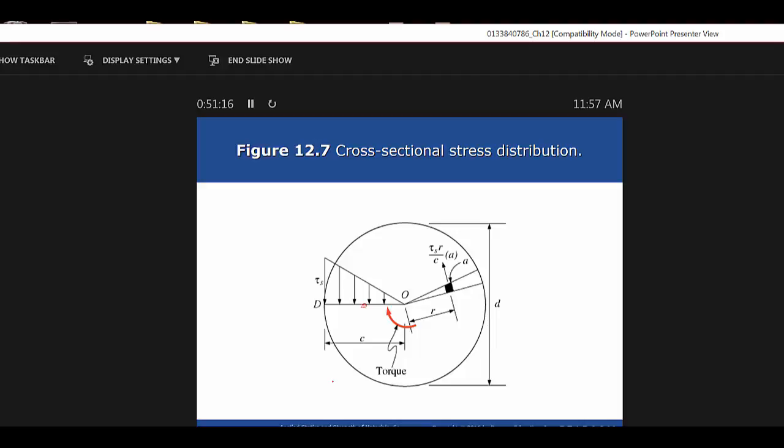What else do we need to say on that? So again, I think I said the shear stress developed in the torsionally loaded circular shaft is proportional to the distance from the longitudinal axis of the member, and the stress equals 0 at the axis and varies linearly to a maximum at the outer surface, which is what that picture depicts for you.